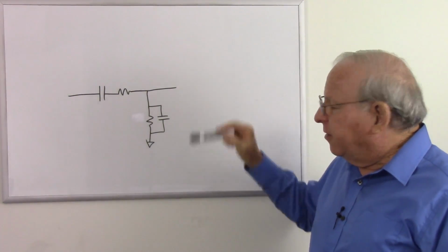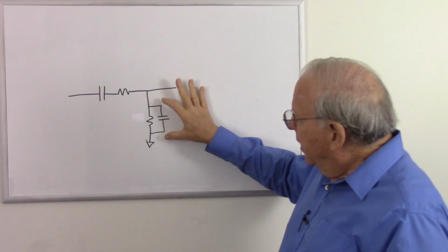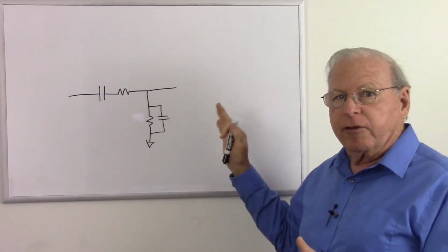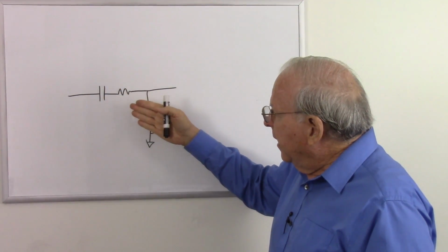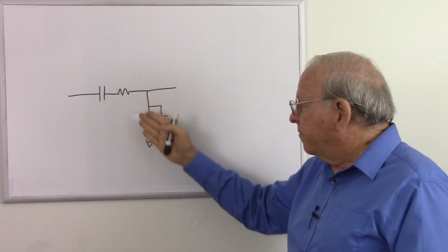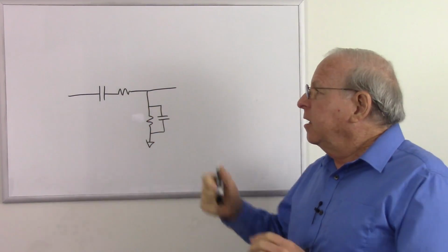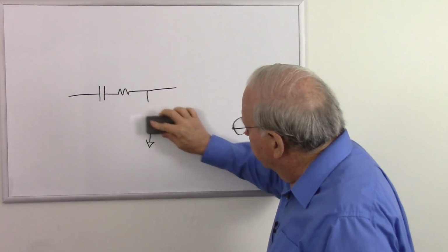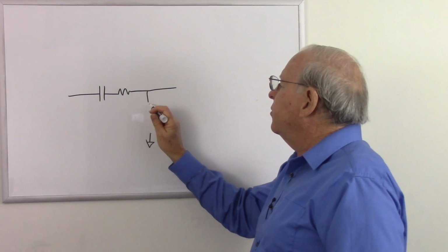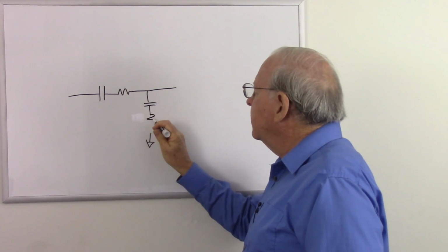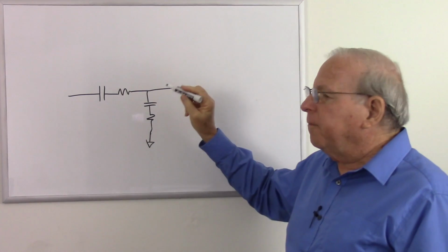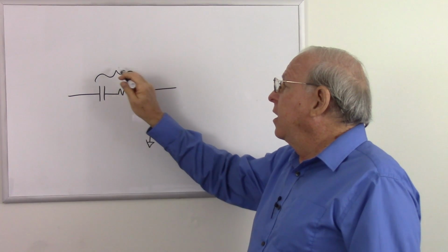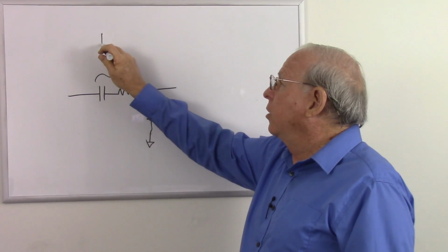First of all, let's see why they are different configurations. So what we have is identical resistors and identical capacitors. We don't need to look at the numbers at this point, just know they're identical. Therefore, the cutoff frequency of this part of the filter and the cutoff frequency of this part of the filter are the same. So now, if they were the same configuration, let's just go ahead and put them both in series. Doesn't matter which one. We'll see that that does not matter in a moment. Let's say they're both in series. Therefore, let's say at low frequencies, the filter elements have an impedance of 1K. So we're looking at low frequencies now.